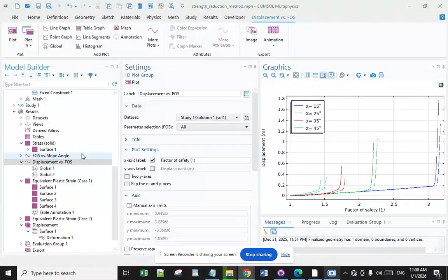The next concept is material dependence. For ductile material like steel, yield strength is used. For brittle materials like concrete, ultimate strength is used. The next one is importance. Accounting for uncertainty ensures reliability and prevents catastrophic failure in bridges, buildings, aircraft, and machinery.